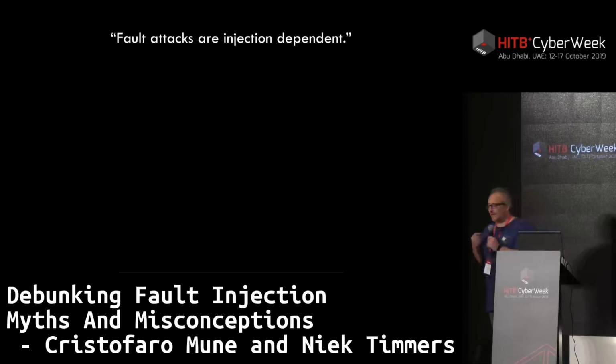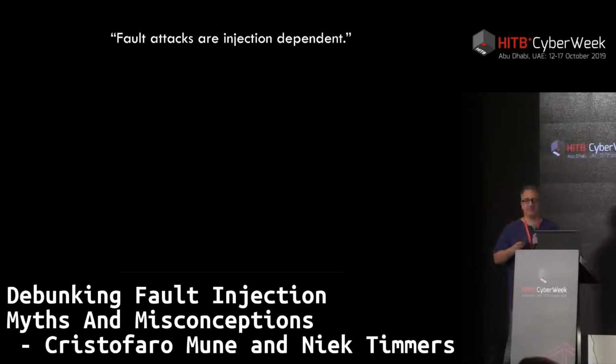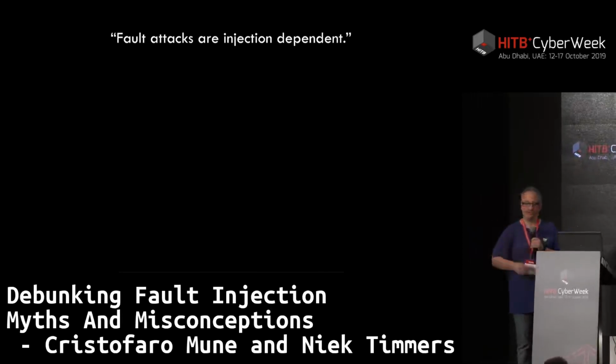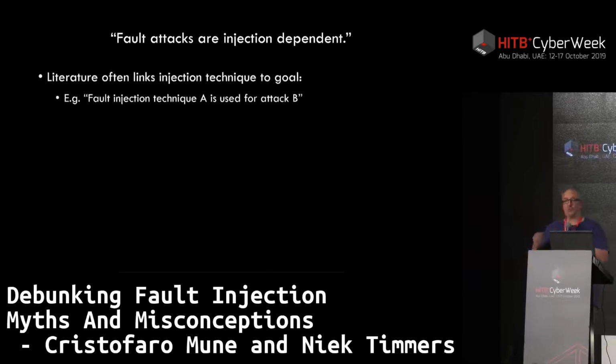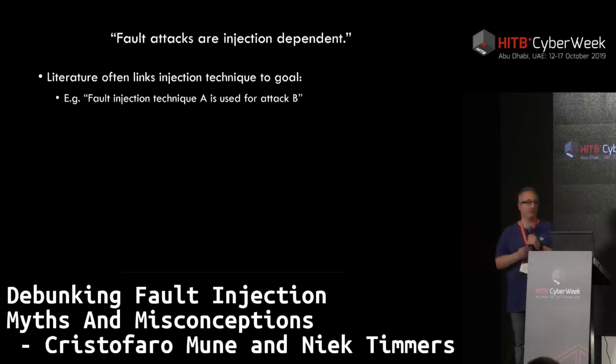Actually, there is a misconception that fault attacks depend on specific injection techniques. I think the literature often ties your injection technique to your goal, like voltage fault injection to bypass secure boot. So you're injecting voltage and then you achieve the secure boot bypass. Or laser injection in order to weaken the RSA key, like you could do that only with laser. For some reason, this idea has been stored in our memory, that we connect the way we inject something with the goal. And this might suggest that if you don't have the technique, then you're not able to reach that goal, which we don't think is true.